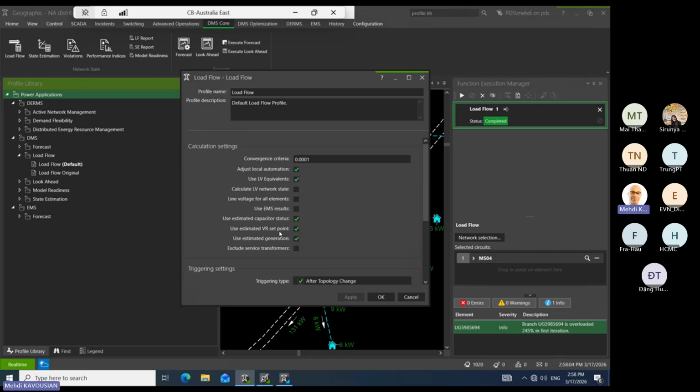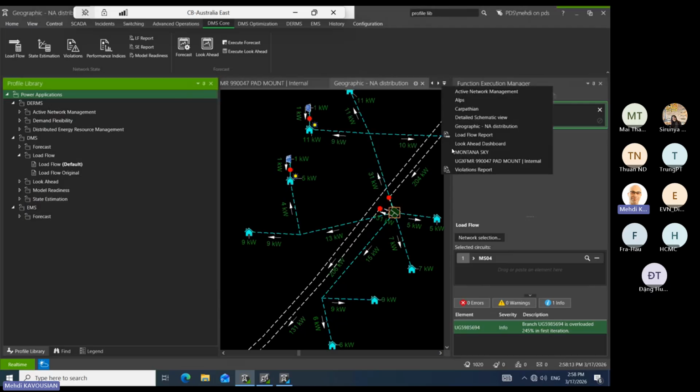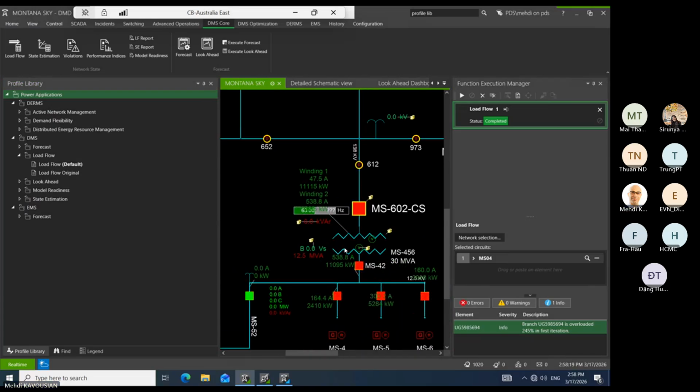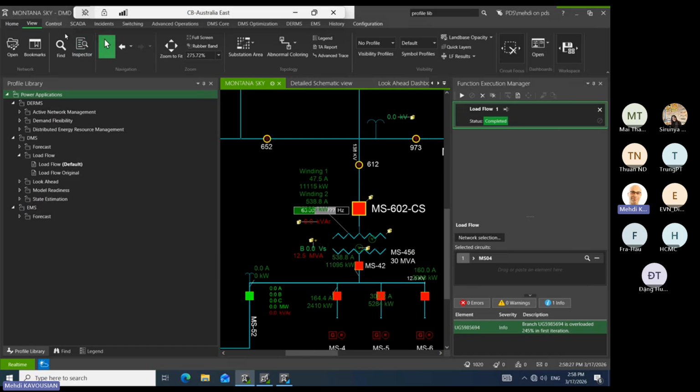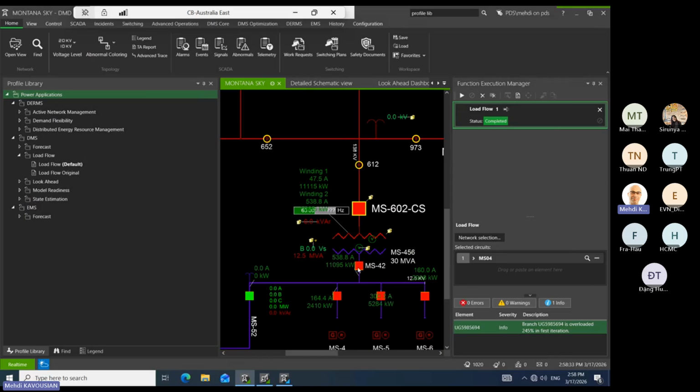This VR set point is the voltage regulator set point. I was talking about the voltage regulator briefly in the morning session. So what is the set point here? Again, maybe for your system it doesn't matter, because this is the transformer. Let me just change it to the voltage level here. So you know what this is? High voltage and low voltage. The regulator here tries to change the tap position to reach a value that we set.